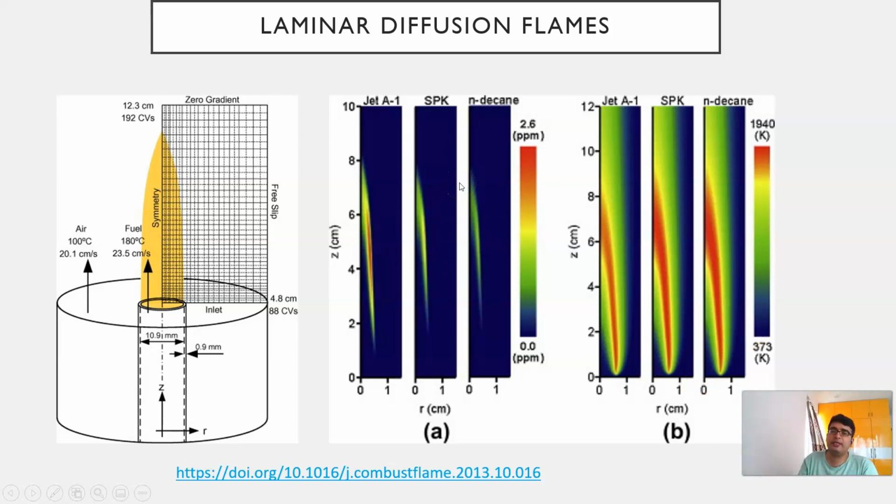And this is also a very common thing, to find the amount of soot that is being generated. Diffusion flames in certain cases produce a significant amount of soot, which are unburned carbon molecules. This is because, while ideally the local equivalence ratio of the flame is equal to 1 and there is no leftover oxygen on the fuel side, usually some oxygen bleeds into the fuel side, inside the jet, and then the fuel begins to burn at an extremely rich stoichiometric condition, away from the flame front.